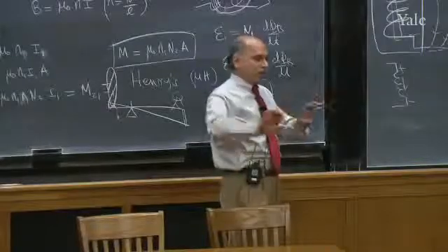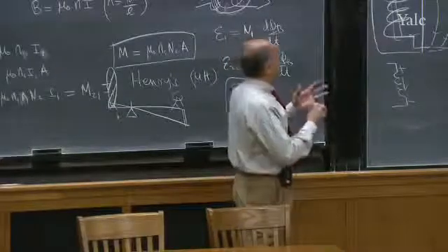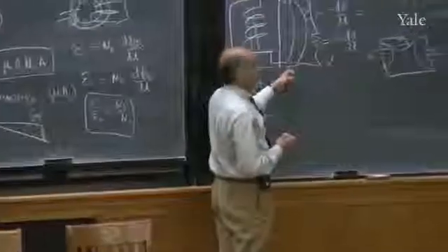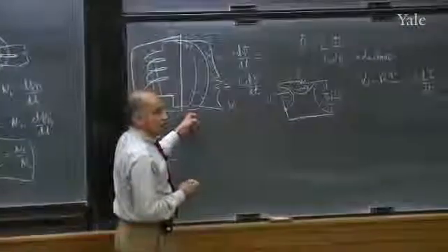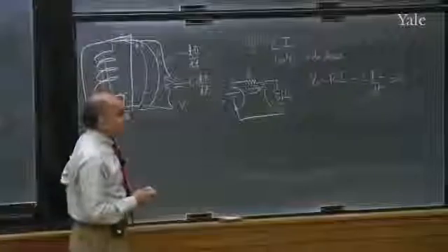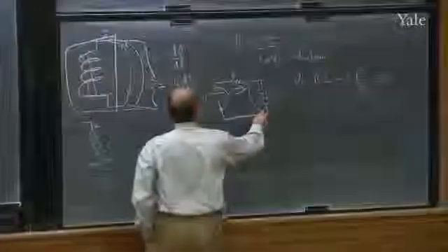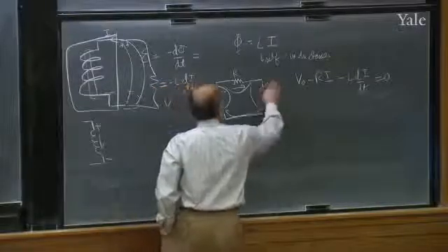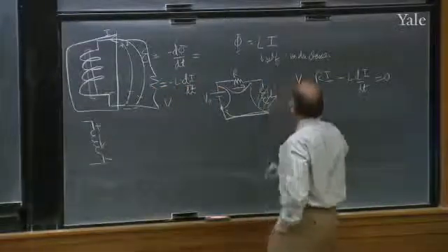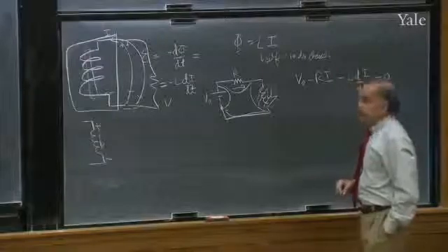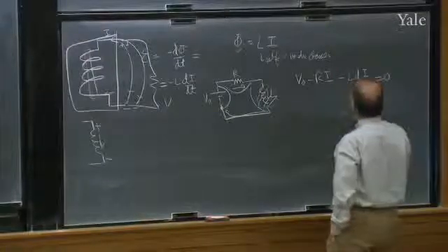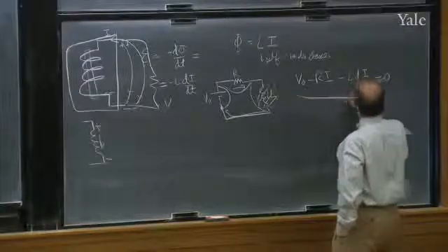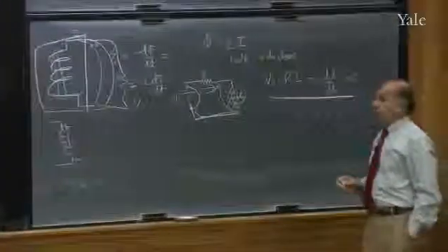But if you come outside the coil, I've tried to show you over and over again, all it looks like is there is a voltage difference between the two plates, the two terminals, and that value is L di dt. So when you do your circuit equation, you go from there all the way back here, you skip these funny elements, and around them, you still have the notion of a voltage. So this is the equation to solve at any time for an LR circuit.